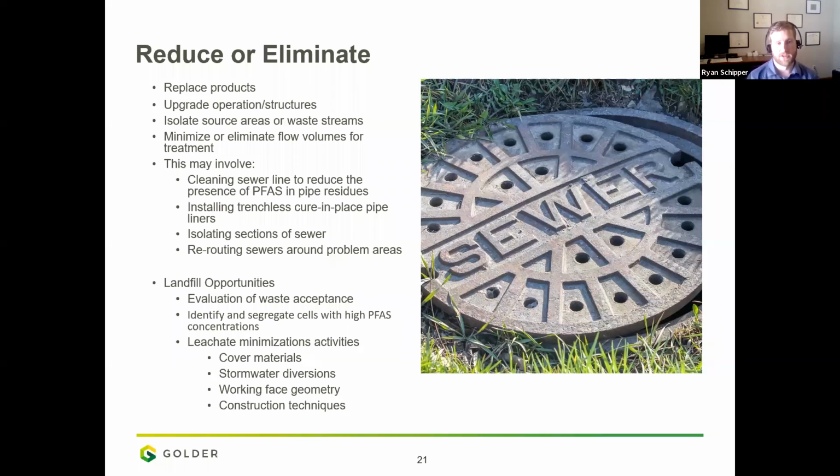And then landfill opportunities, which again we'll touch on a little bit later, but you can look at evaluating your waste acceptance, with additional testing there. You can identify and segregate cells with PFAS concentrations. Some of the different cells within the landfills can have very different PFAS concentrations depending on what wastes were accepted. And then obviously leachate minimization activities, looking at daily cover, intermediate cover, accelerated final cover to reduce